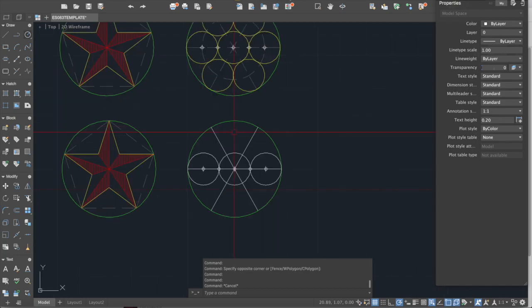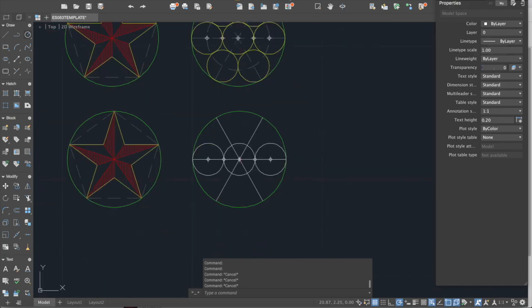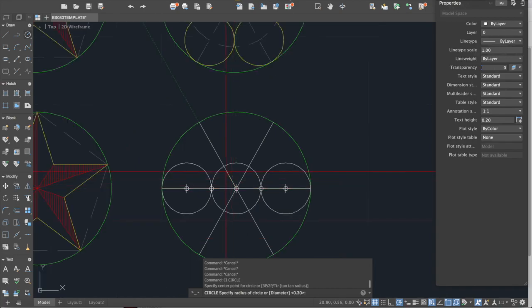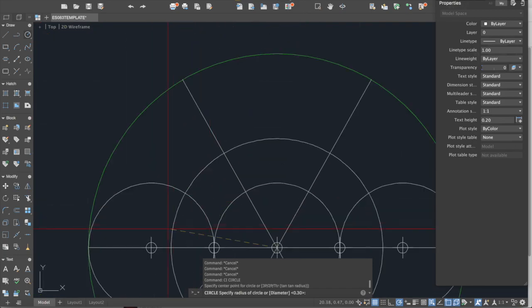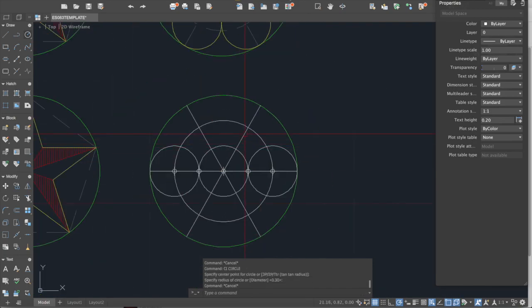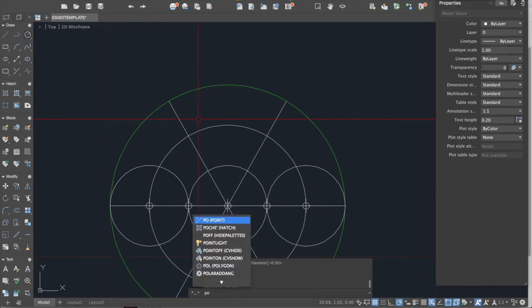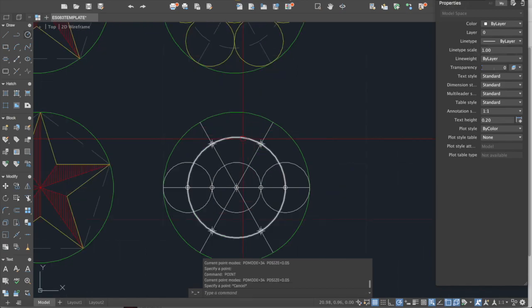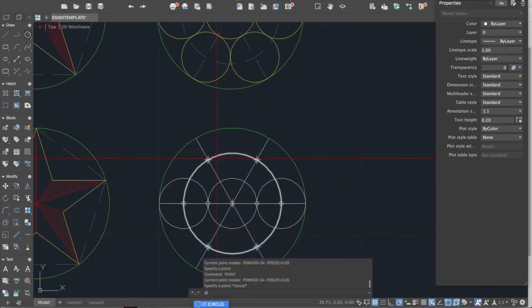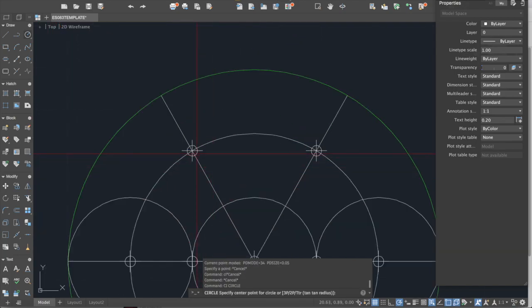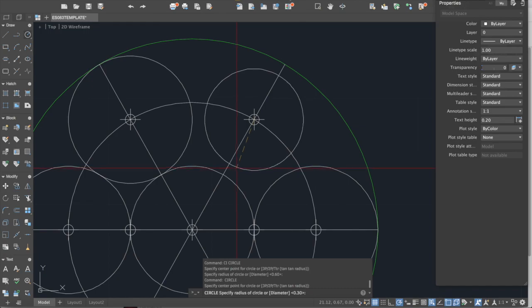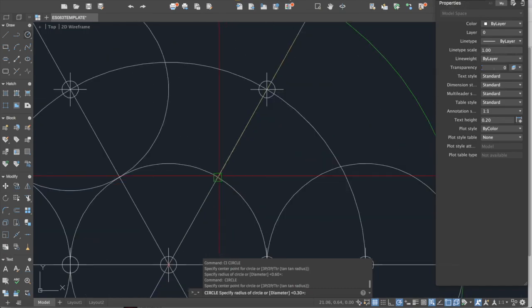So what we will do is create a circle and then start from the center, click, this is the midpoint, and then our endpoint will be the first point, which is this one. Click. So now we will place a point around here. So these intersections will be the midpoints of the other circles. Okay, so let's try to place now the remaining circles. So type in circle, enter. Then we will have this first midpoint, and then its endpoint will be towards the endpoint of the other circle. So this one, same as the opposite side, towards the endpoint or intersection of the circle in the center.